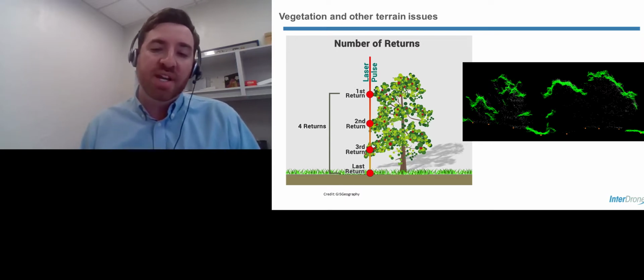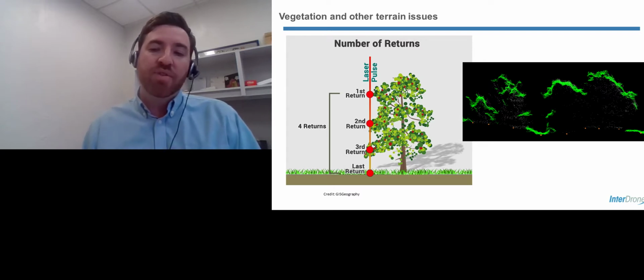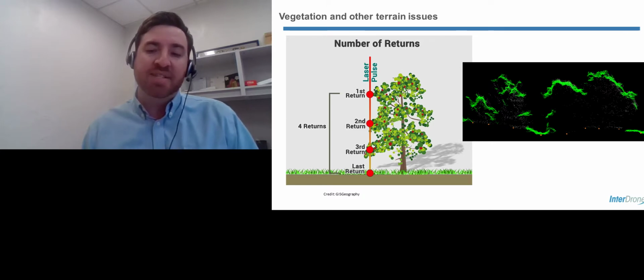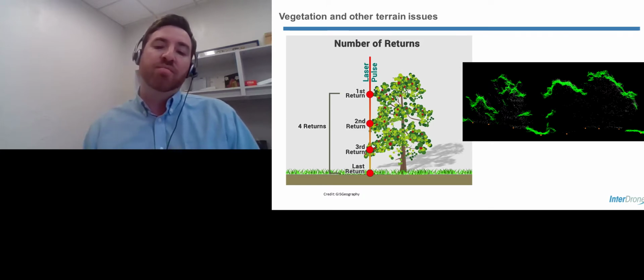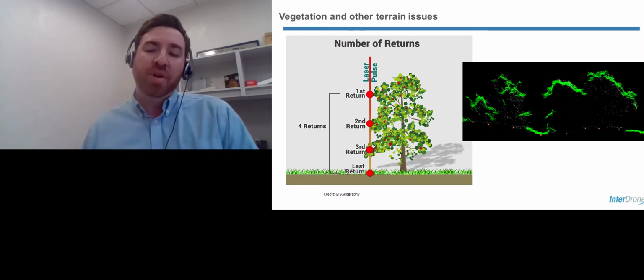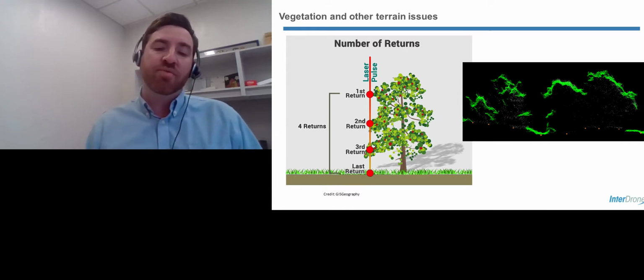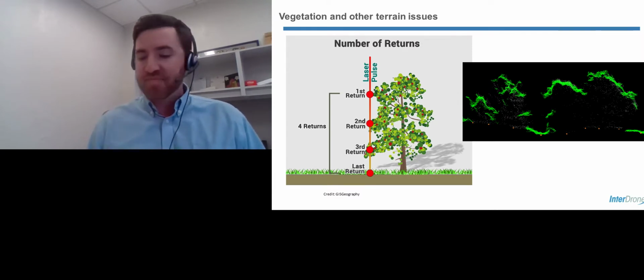The green is based on imagery only, and the white, where there's more information down underneath those trees, is based on LiDAR. This is a drone project where the structure from motion, or the point clouds built from imagery, was leveraged, but we also used LiDAR because we knew vegetation was going to be a problem.